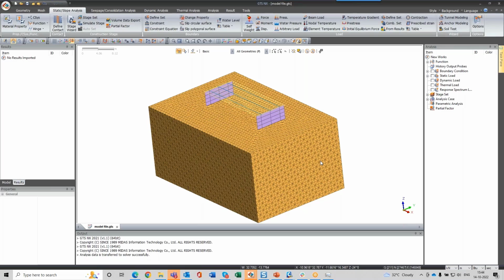So the important thing over here is the traditional finite element tools generally cannot deal with the large strain problems, because in case of large strains, there is no equilibrium condition happening over there. But in the finite element solver, each and every step has to be in equilibrium, and that is where the implicit solver comes in. In the implicit solver, you will get the equilibrium in each and every stage, but when you go for large strain problems, there is an issue because the entire state of the model itself is not in equilibrium. So implicit solver cannot do it.